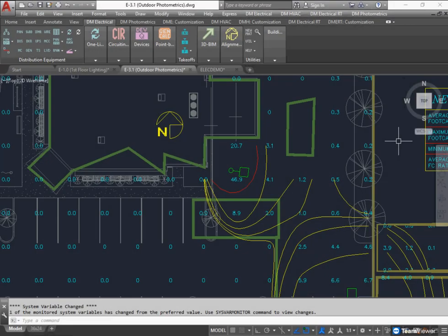All right, so the first question is linear LED lighting is getting more and more popular. You can often order custom lengths of light, but the IES file is set up for a specific length, such as 4 feet. So if you have 12 feet of light, how do you best model that with the software? The answer is that you need to have a single light fixture for the 4 feet representing the IES file. And then if you have 12 feet of light, you just put 3 of them back to back to get the 12 feet.